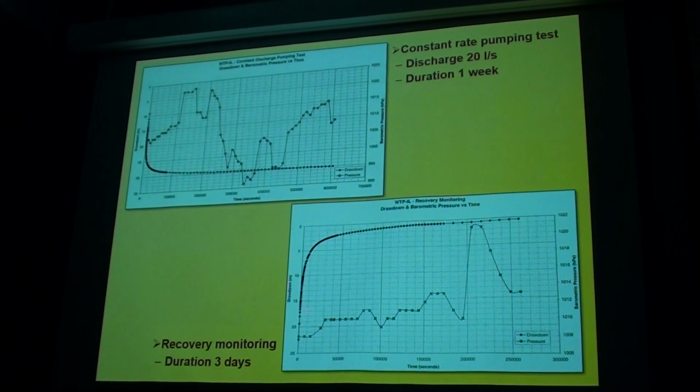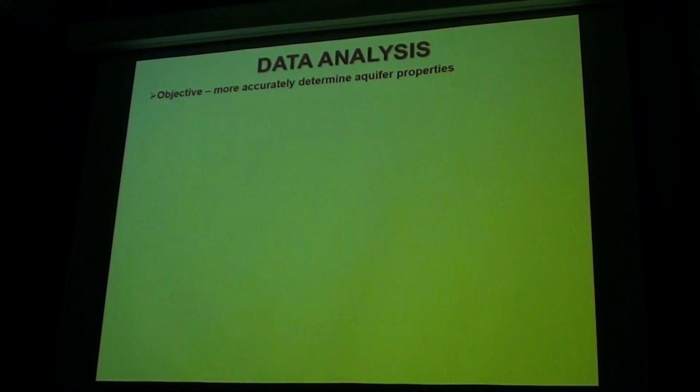Drawdown data during pumping testing. Recovery data after pumping testing stops. So this time here is the time since you turn the pump off. This time here is the time since you turn the pump on. It's important to make a distinction between those, because that will come into our calculations later.